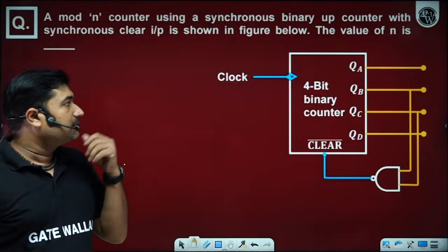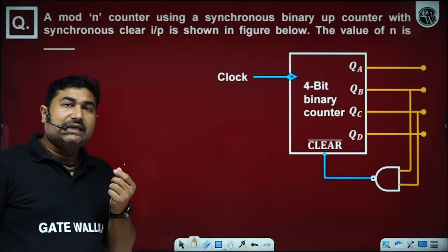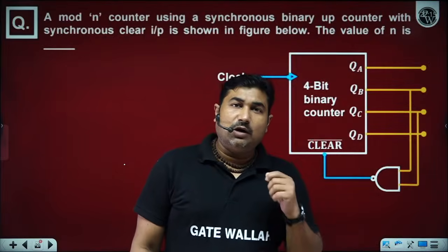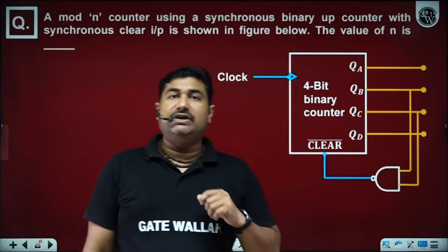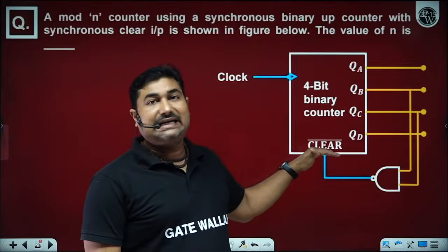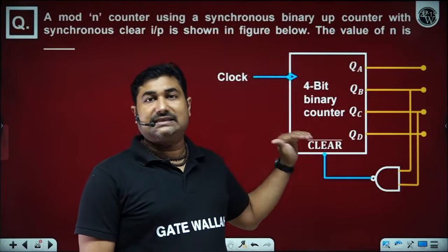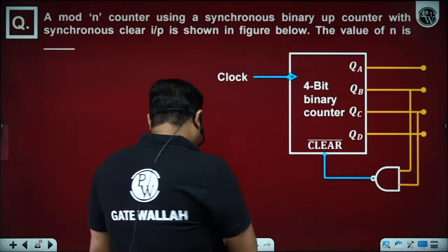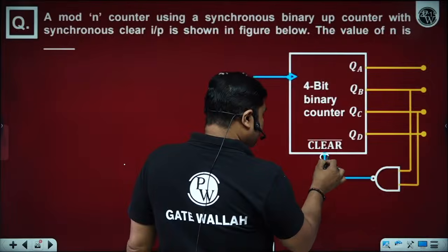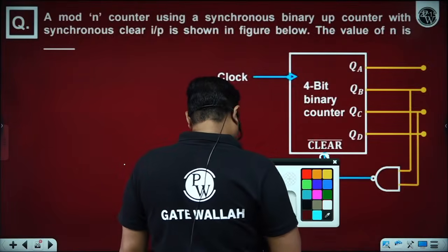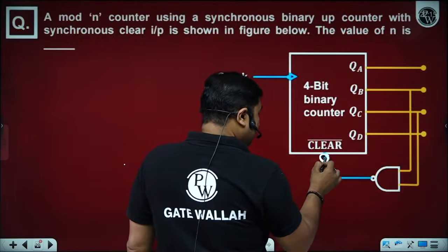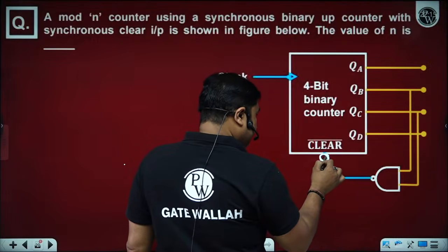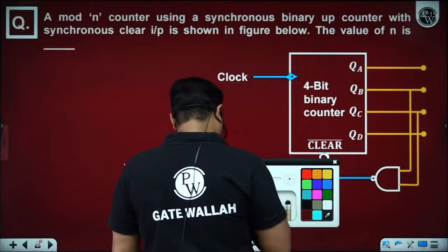Now please observe here. We can also design non-binary synchronous counters. While designing non-binary synchronous counters, again we will use the concept of preset and clear. Sometimes a bar is present just before the clear pin and then it becomes clear bar. This is very similar to the non-binary ripple counter we have studied.